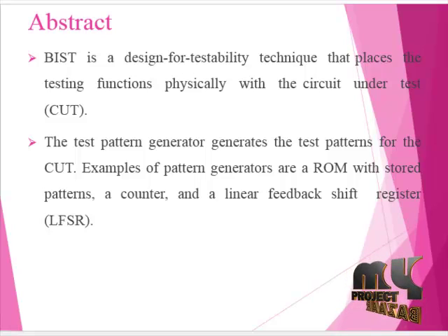BIST can keep average and peak power below a given threshold. The test power can be reduced by preventing transitions at memory elements from propagating to combinational logic during scan shift. This is achieved by inserting gating logic between scan cell outputs and the logic they drive. During normal operation and capture, this logic remains transparent. Gated scan cells are also proposed. A synergetic test power reduction method uses available on-chip clock gating circuitry to selectively block scan chains while employing test scheduling and planning to further decrease BIST power in the Cell processor.